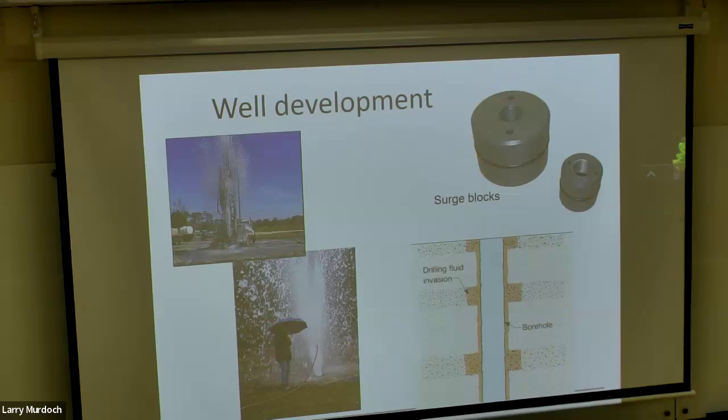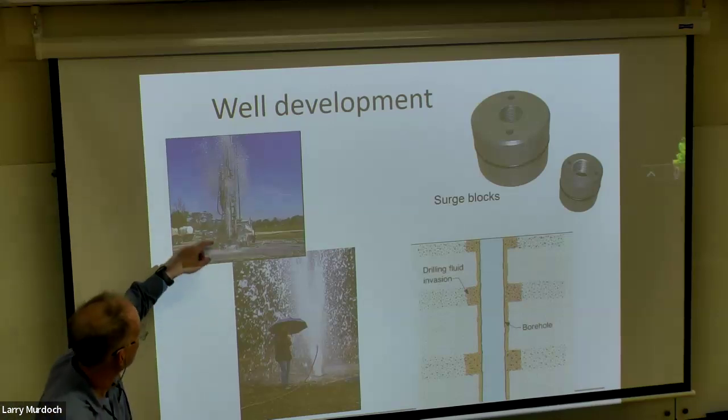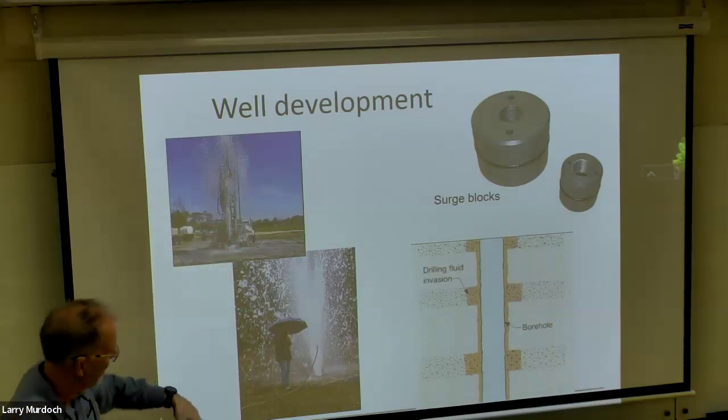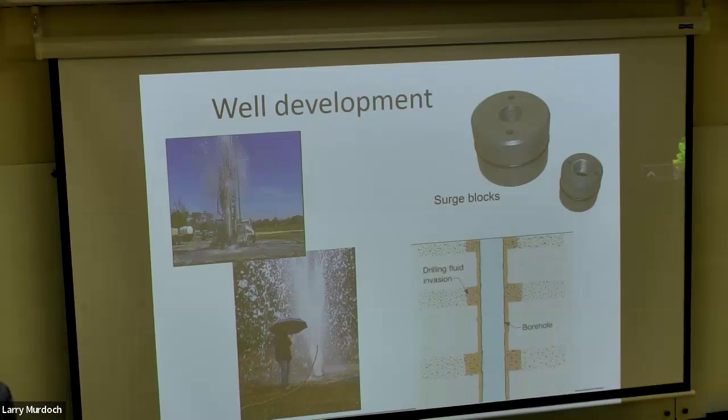So there are more aggressive techniques. One technique called airlift is to put a pipe down the well, strap the pipe down, hook it up to a big air compressor, and inject air really fast down below the water. That shoots all the water up in the air and removes the water very rapidly.